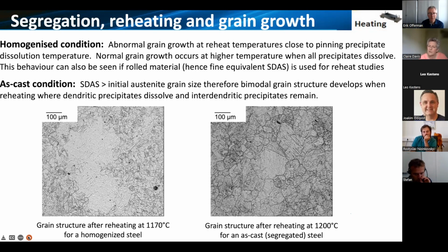And carrying out reheating trials there, we actually found we could make the material show abnormal grain growth, because now when the grains started to grow, they had enough driving force, because it behaved almost as a homogeneous material, because the length scales between any of the segregated regions were very much finer. So one of the things that we know is that ensuring we avoid these non-uniform grain structures, we do need to take into account what's happening in a representative as-cast microstructure, not always just a lab microstructure.